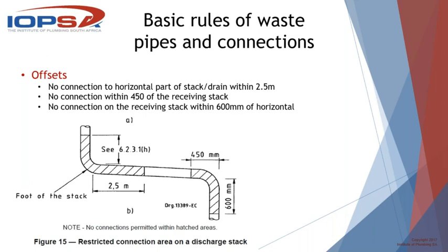We as plumbers had to notify developers many times that HVAC condensation water pipes were joined to the sewer stack. This seems to be a common thing that we encountered almost on a daily basis. We are asked to reroute these many times. Yeah, I've seen that so many times myself. There's an assumption that there's a drainage pipe, so I'll just drill a hole, stick my pipe in, have it protrude an inch into the discharge stack, and put some silicone around it, and that's okay. It's a big problem.